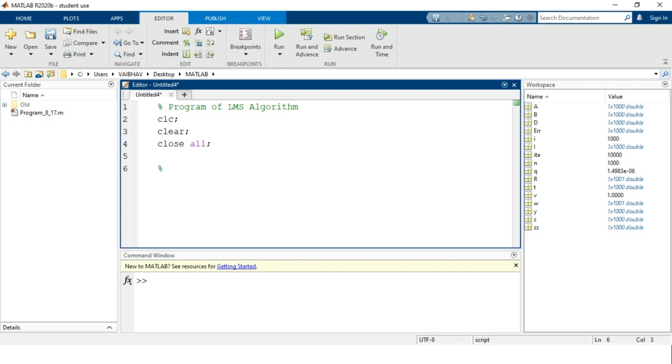So I just modularize the statements in this MATLAB environment. A comment here: generating desired signal. For generating the desired signal we require the time parameter. So let us note it with small t, and here we define small t, the time parameter that will start at 0.001, with intervals of again 0.001, till it attains the value 1.